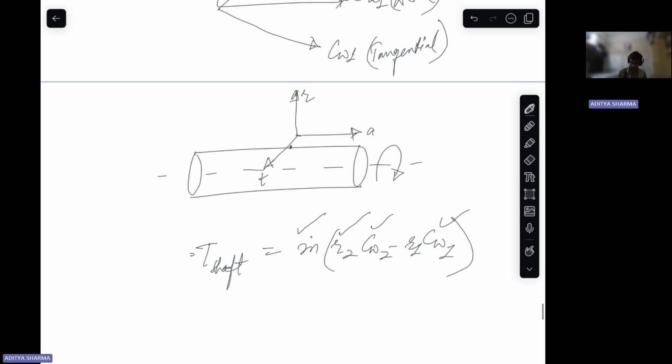This is for a compressor. Okay. Then also the pressure change across the turbo machine. What is its relation with the velocities? So for your compressor, the pressure change can be related to these two velocities. One is your shaft moving, and the other one is your relative velocity.